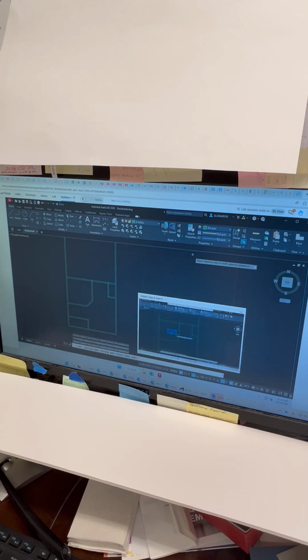All right, for everybody else, here's what I want you to do. I want you to start the offset command, and I want you to offset that diagonal line anywhere above that diagonal line. I want you to offset it by the thickness of a wall, which is 3.5 inches. Start the offset command. Type in a distance of 3.5. Hit enter, and then offset that line anywhere above to this side. Just click to offset the line, all right?